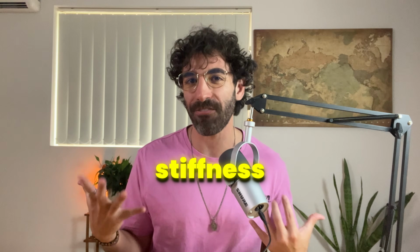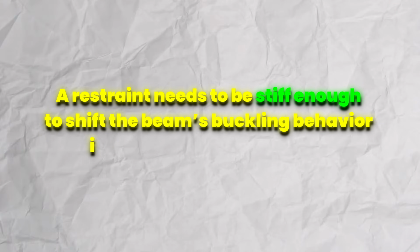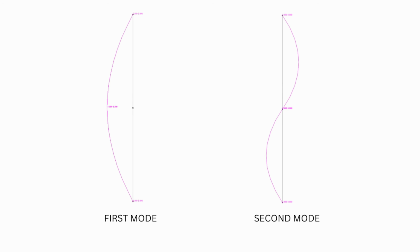It's all about stiffness. A restraint needs to be stiff enough to shift the beam's buckling behavior into higher buckling modes. I'm gonna repeat that again because not even I understand what I'm saying. A restraint needs to be stiff enough to shift the beam's buckling behavior into higher buckling mode. Just like how adding a stiff restraint at mid-span of a compressed column forces it into a second mode buckling shape instead of the first. And it's the same principle.